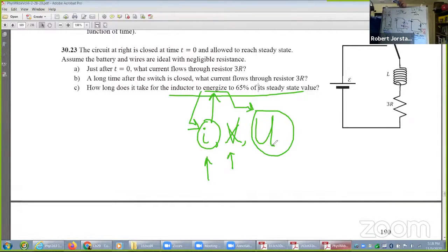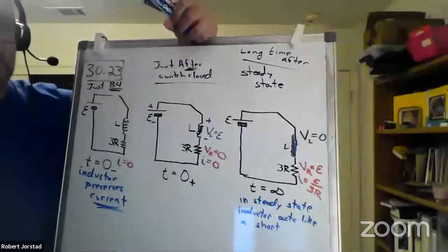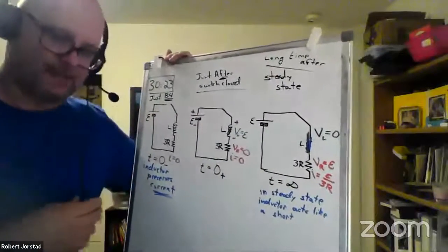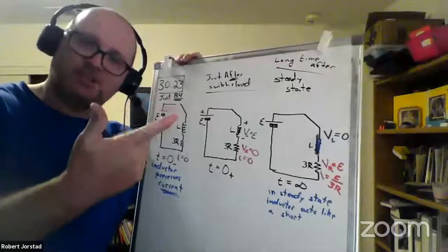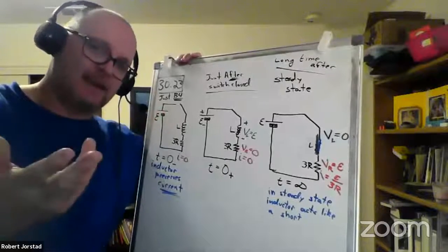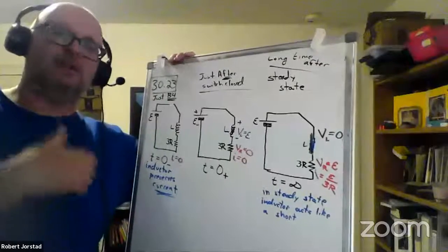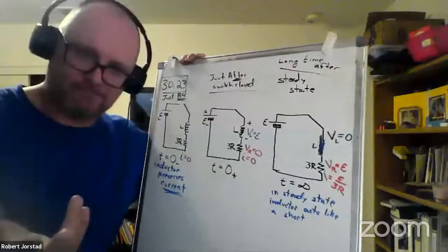Now, do you guys know any equations? Let's go back to capacitor land for a second. Let me get this off the screen. So if we pretend we're doing RC transients again, we could find the voltage and the charge really quickly. How would I get the energy as a function of time? I'd plug it into U equals 1/2 QV.